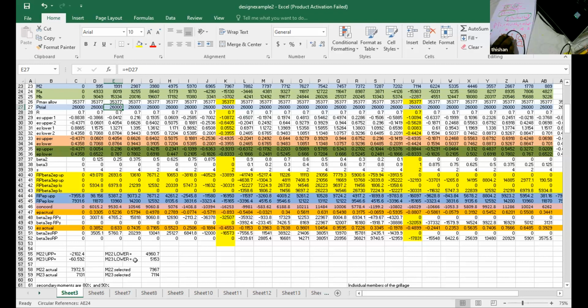If you are getting both negative or both positive, there's no 0 in between. That means the pre-stressing force selected is insufficient, and you are trying to fit a bending moment diagram to a set of limits where no bending moment diagram ever exists. So whatever the load combination you select, you can never ever fit a bending moment diagram into those limits. Even if you try for 1 year, you will never fit it, because there's no single bending moment diagram that can be fitted inside.